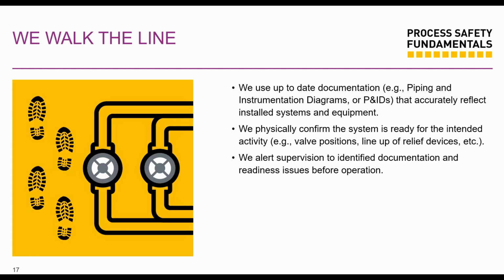Then the sixth is walk the line. So we use up to date P&IDs. Once you're an operator, you need to honestly constantly walk your line. This is done with your P&IDs. So are your P&IDs up to date? You have a change here. Has it been effected in your P&IDs? And make sure that the site, the plant, accurately reflects everything that's installed. You have a drain valve here.